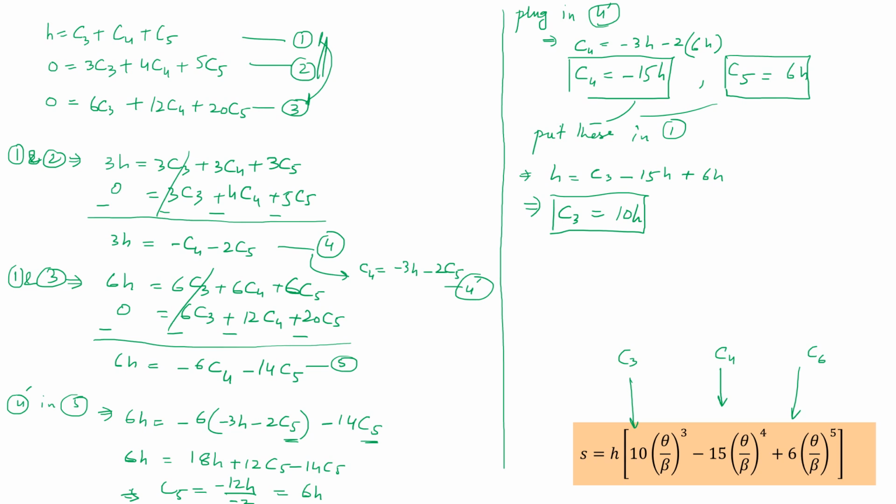So in this realization, you can now see that the polynomial corresponding to position of the follower has been specified, and this contains the powers of 3, 4, and 5, and that's why this is called 3, 4, 5 polynomial in the initial discussion that we had. So this is for 3, 4, 5 polynomial.